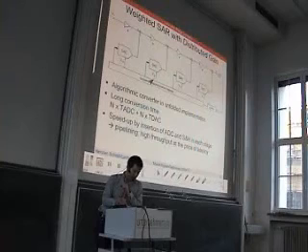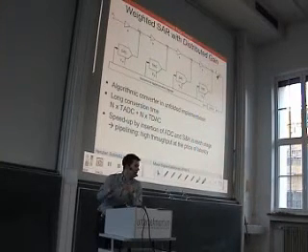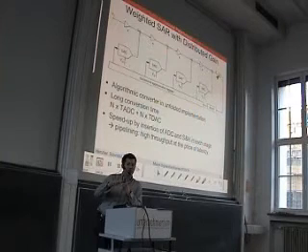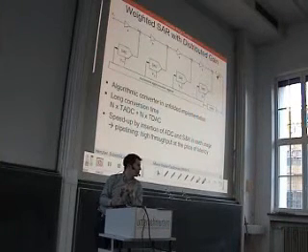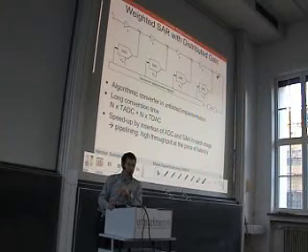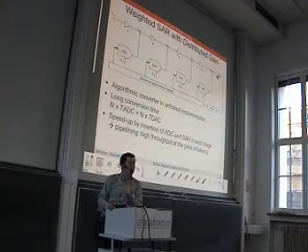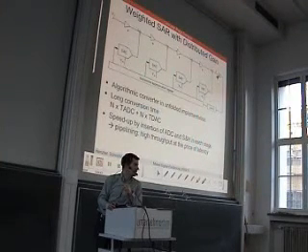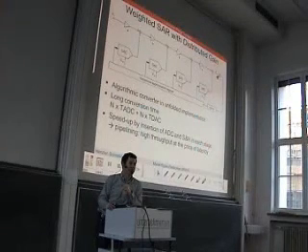Then at the end we get a new voltage here, and then we have to check the sign again. So we have n DAC conversion times, and we have n comparator delays, and in good approximation we can assume that the digital delay is negligible. Okay, so everything has to be done n times. So any idea how we could accelerate this?